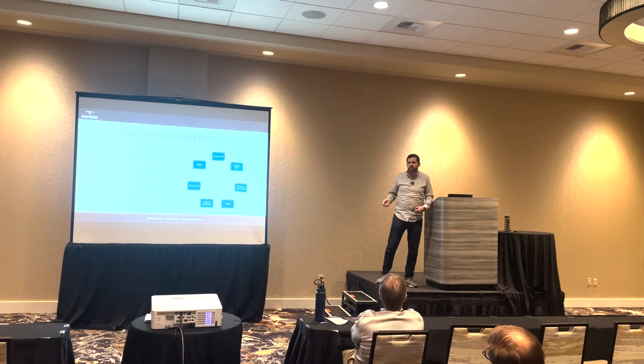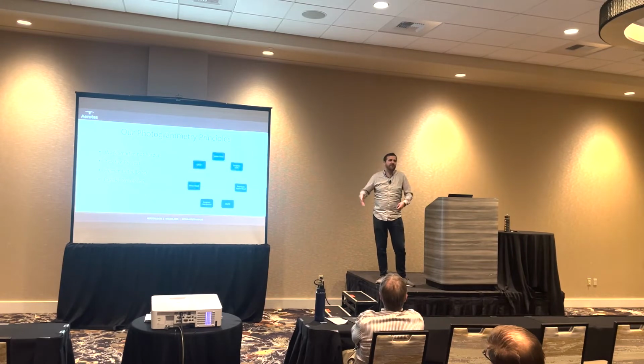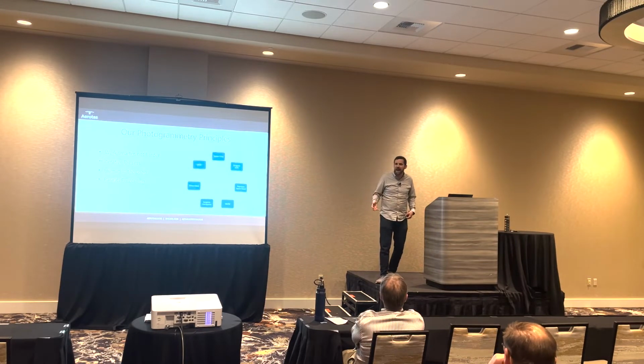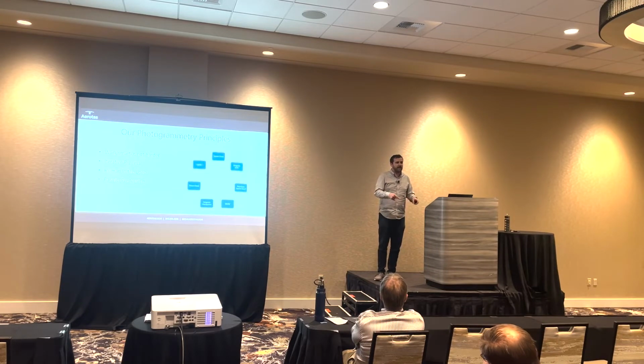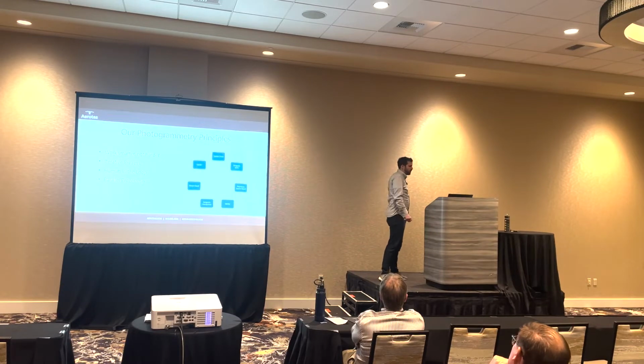Especially in a world like survey, where you can't deliver half-baked products and expect your clients to come back. If you say, here's a curve line, and it's 18 jaggedy, disconnected polylines with a couple tenths between them, that's not good enough for a client. It needs to be a nice, smooth curve for an engineer that's going to actually deal with it.